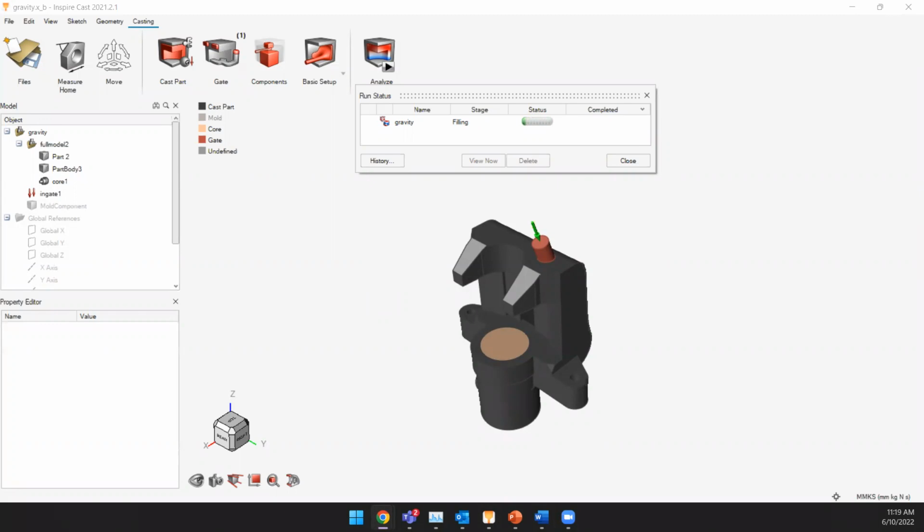So it is typical in the industry to first design a process and then simulate it, but Inspire Cast turns that concept on its head by helping users evolve the process in tandem with their ideas. You can start the filling with virtualized in-gates like I showed, and that will guide you through the areas of porosity and the right risers to compensate.